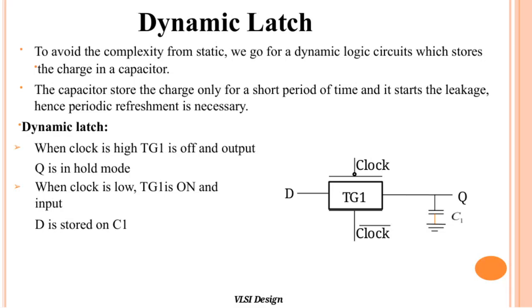To manage complexity, we use dynamic logic circuits that store charge on a capacitor. This capacitor only holds the charge for a limited time because it leaks, so we have to refresh it periodically to maintain the stored value.